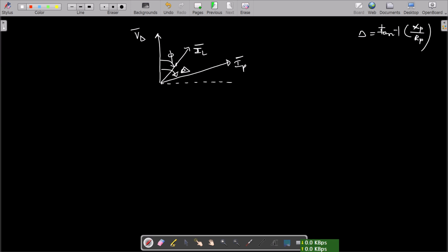For an RLC circuit, that power factor angle will be given by this equation, already known from circuits. Also we know that whatever series flux is produced by the series magnet, that flux will be proportional to this current, because the load and the series magnet coil are in series. And phi sh will be proportional to the load voltage, because VL created IP and IP created phi sh.